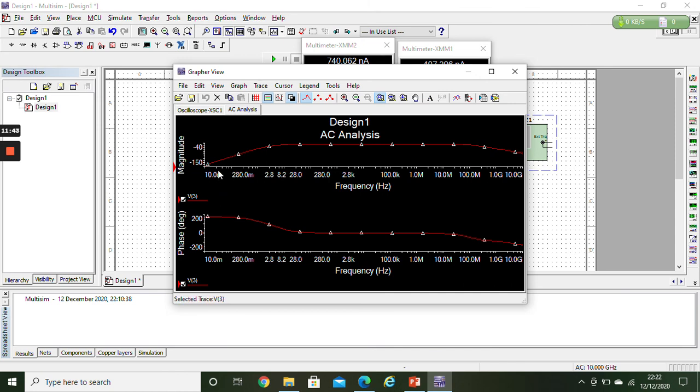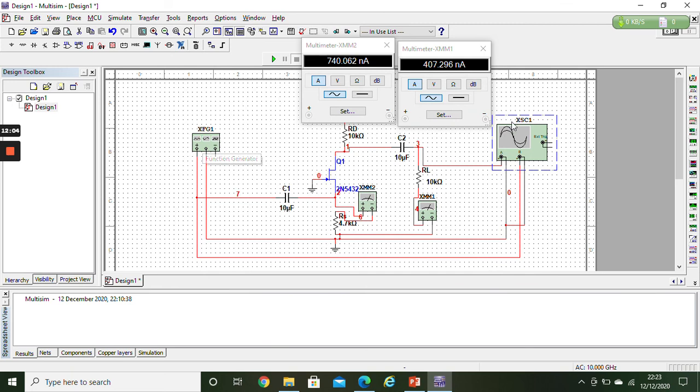And you are starting with a frequency of 0.01 which I chose, and going up to 10 gigahertz. So this is how your plot would be, and you can add this plot in your lab copies as well, but do add a plot of your calculated values by changing frequencies manually, right? Okay, here you will change your frequencies, and plot accordingly the V output and V input values that will come; those would be used to calculate the gain, and with this you fill your figure, the plot. Finally you will draw a graph, right?